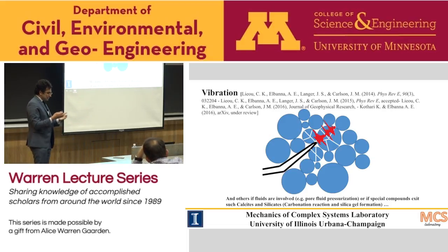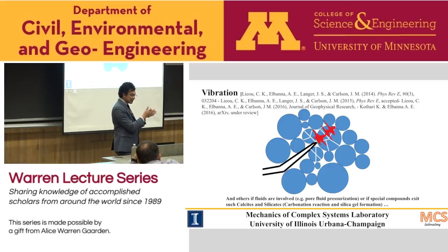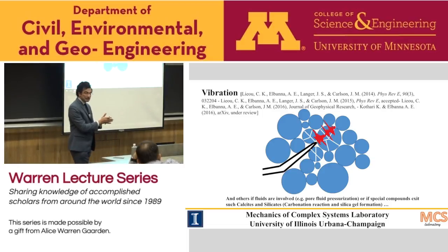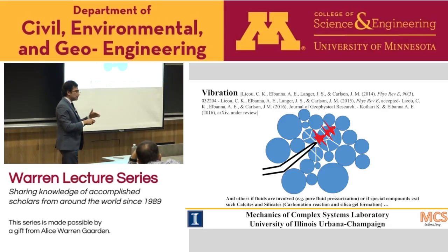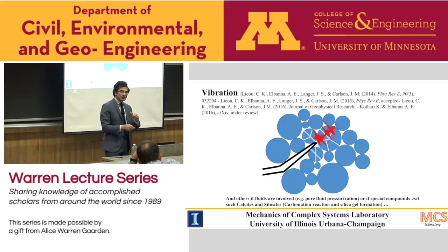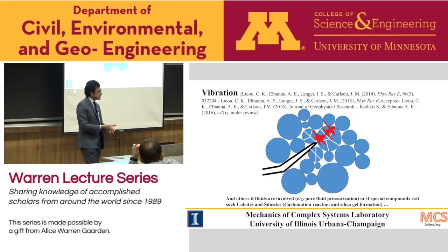Or, something that we would like to do is, if we look at the crack or the shear band, locally we expect to have high frequency oscillations and waves emitted from the crack tip. And these waves would probably cause compaction of the granular material ahead of the crack tip. So we'd like to look into two things: either externally applied vibrations or internally generated vibration in the granular layer.